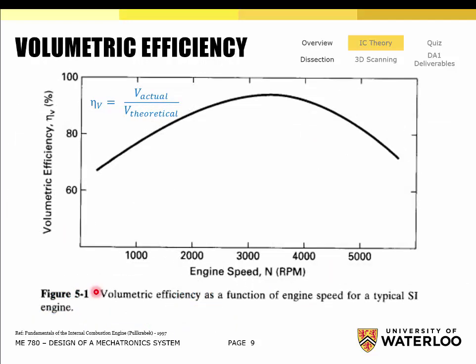So we're looking at this process in a quasi-static sense. We're slowing it down as if we had a super slow motion camera, okay? But everything here is occurring with some time associated with it. The combustion process takes time. The scavenging process of the intake and the exhaust, they both take time. And each of those things actually happens most efficiently at a certain speed or frequency. Because of that, the engine naturally breathes better at a certain frequency of operation.